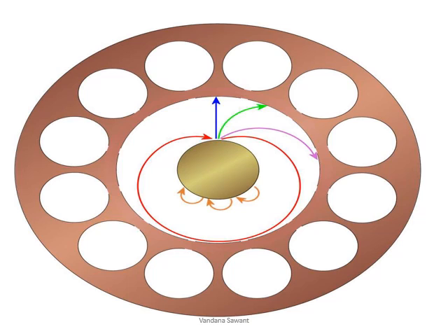So in this blue path, the electron comes out of the cathode and moves directly to the anode. Second, if we increase the magnetic field by a little amount, then it will take a slightly curved path as shown by the green arrow. Then if we want to give maximum energy to the cavities, we should take the curved path indicated by the violet color arrow.